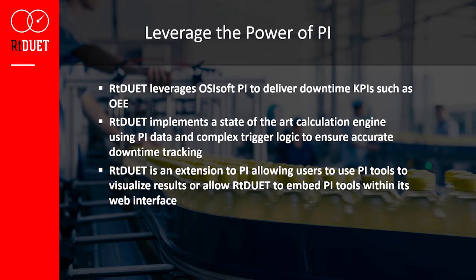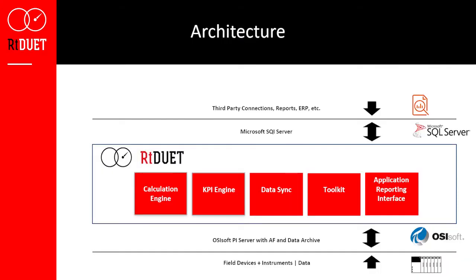And so we can tell when parts of your plant are down, and then we can calculate your downtimes and the reasons for those downtimes. And then with that information, we can calculate your KPIs. So in power gen, that equals all the power gen KPIs. In other industries, that's other KPIs like OEE and availability. But for power gen, it's more like your availability factor or your unit derate factor, and those kinds of KPIs.